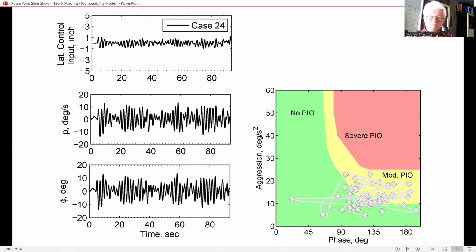This prevents the pilot from attempting to maneuver the aircraft into an unacceptable attitude or approach too near to the limiting angle of incidence or exceed the structural limits of the aircraft in a maneuver.